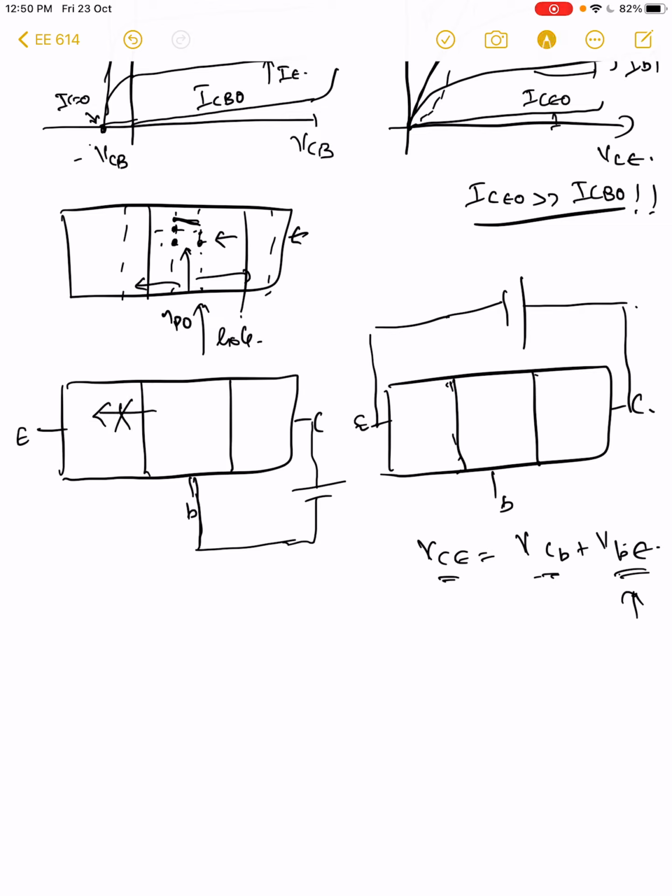If there are no currents here, there is no electron gradient here, so the electron concentration remains flat. Because we are talking about the ideal situation where the current is mostly carried by diffusion, the loss of electron gradient in this particular part of the BJT significantly reduces the base emitter reverse bias current, even lower than the normal reverse bias current.